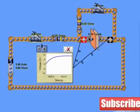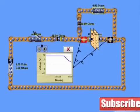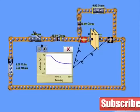If we look at the discharge curve, since our values are the same, we should see the same time. Coming down from 9 to 4 volts is going to be our RC time constant. Let's try that. 1,000, 2,000, 3,000. So this circuit has an RC time constant of approximately 3 seconds. Let's take a look at that one more time.